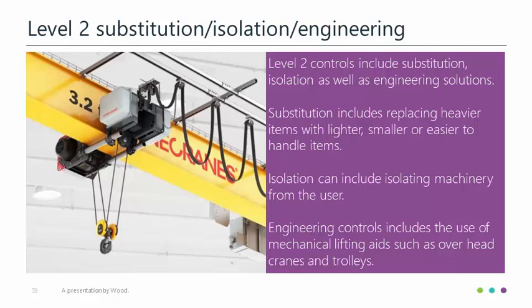I spoke earlier about our positive purchasing policy at Wood, as when you are unable to eliminate a risk, the next level of control is substituting the hazard for something that gives a lesser risk. When it comes to vibration, we use low vibrating tools as far as is reasonably practicable. In addition, where we can, we also use hands-free cutting tools such as clamshell cutters for heavy pipe work or chain-mounted reciprocating saws. But this is not the only type of substitution that you could consider.